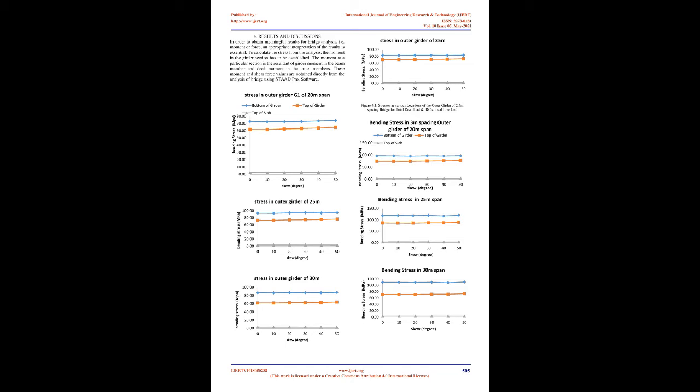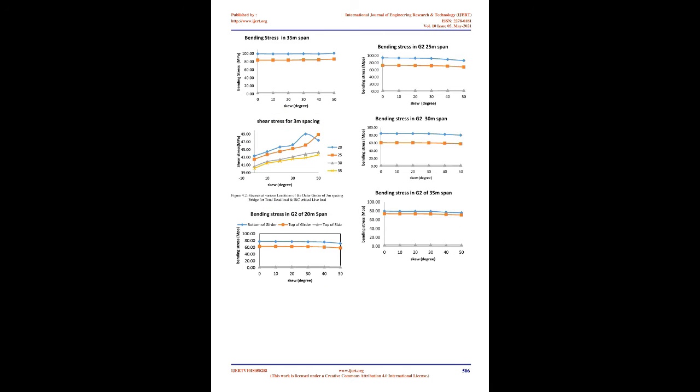In this study of stresses, a bridge is idealized as a single longitudinal girder and analyzed for one train of loading, regardless of the transverse dimensions and properties of the bridge. The forces developed in this system are determined using basic structural analysis methods. Bending stress is equal to bending moment, M, divided by elastic section modulus, Z.